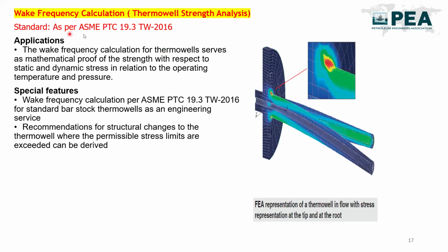So what we do is check the thermowell strength analysis calculation or wake frequency calculation as per a standard, and that standard is ASME PTC 19.3 TW 2016. This is the latest standard, 2016. Earlier it was 2010. It will always be asked of you what standard we use to do the wake frequency calculation or strength analysis of the thermowell. That will be as per ASME PTC 19.3 TW 2016. So these are some vibrations in the nozzle of the thermowell.